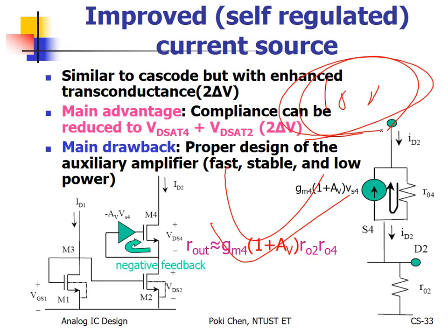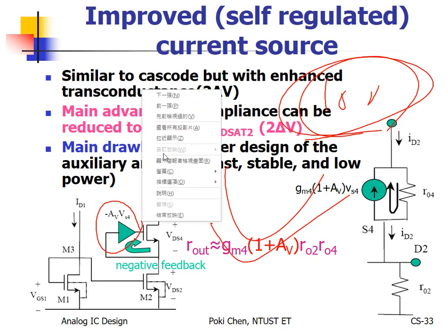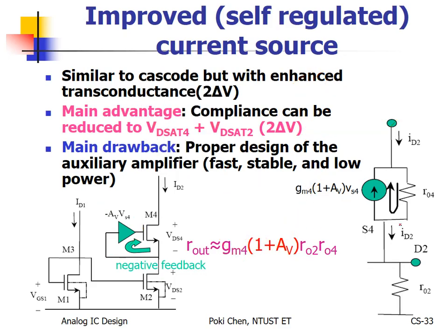For example, your bandwidth will be enhanced by 100 times. Your linearity will be enhanced by 100 times. Your error will be reduced by 100. Only if the gain is high enough, you can reduce your gain through negative feedback to improve almost all the other parameters. That is a very good and very important idea for analog IC design, so we apply negative feedback again and again.